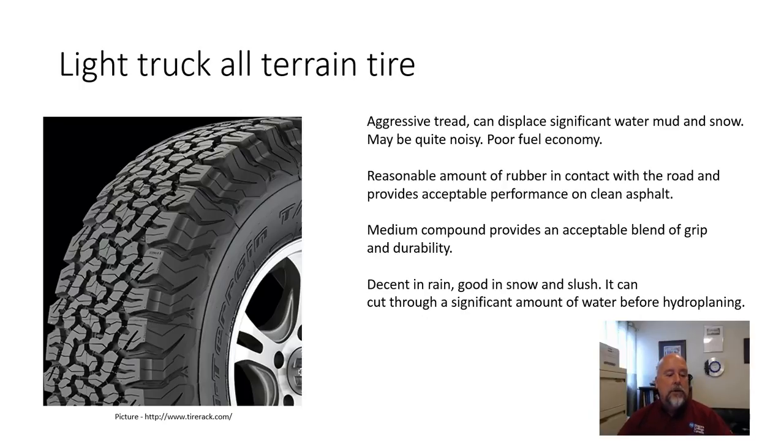So an all-terrain tire like this is fairly commonly used. With a tread this aggressive, you'll find that it's going to be noisy, and they work acceptably on asphalt. They work far better than an all-season radial off-road. So your compromise moved from road performance to off-road performance when you select a tire like this. They can be used on trucks all year long. You'll no doubt see them around, a pickup truck going down the highway in the middle of the summer with a set of tires like this. And if you're driving along beside one, you'll hear the tires rolling. They tend to be quite noisy.